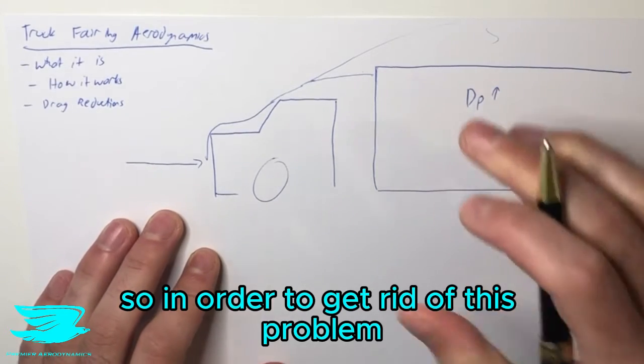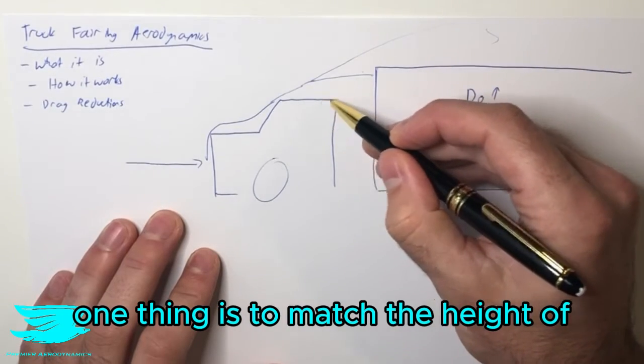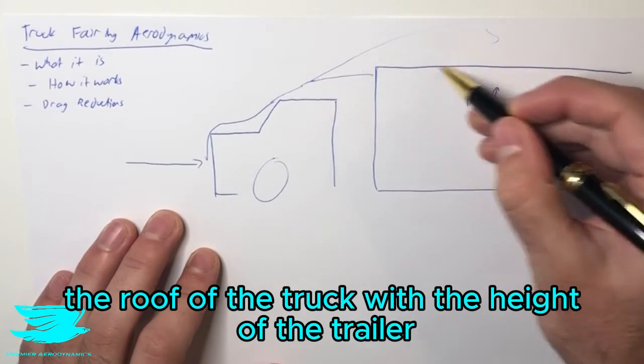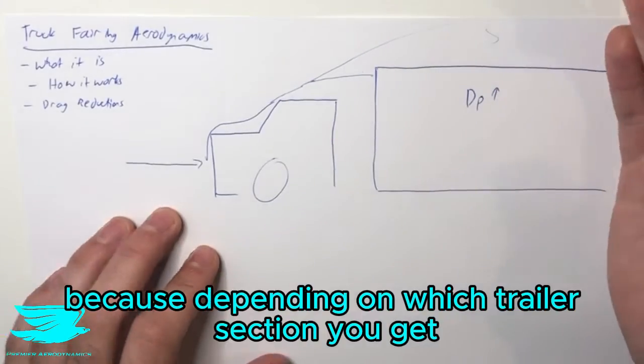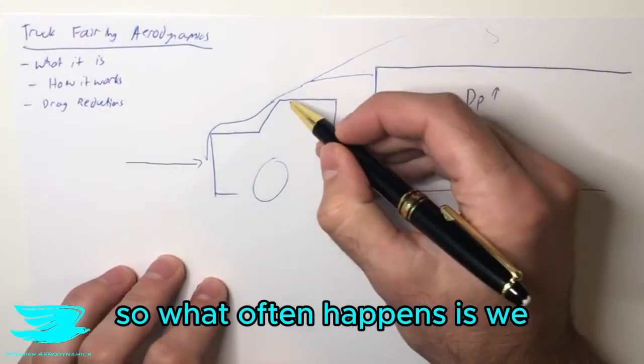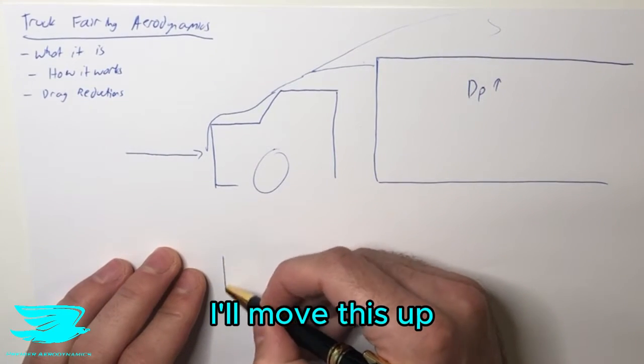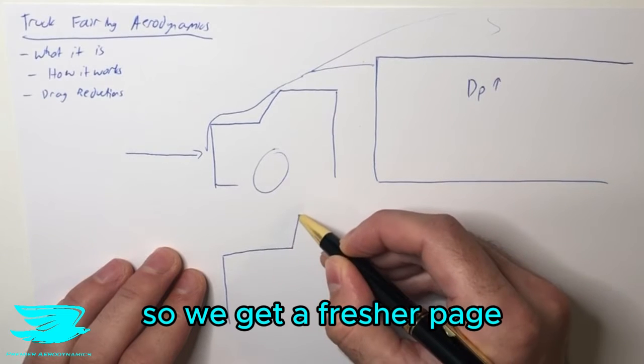So in order to get rid of this problem, there are a couple of things we can do. One thing is to match the height of the roof of the truck with the height of the trailer. That's not always possible because depending on which trailer section you get, that changes. So what often happens is we put something called a fairing on here. So let me draw it again here. I'll move this up so we get a fresher page.